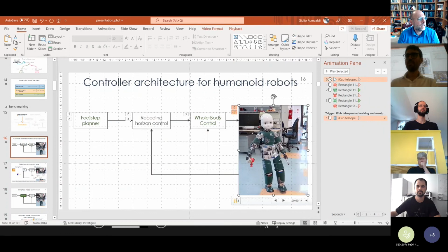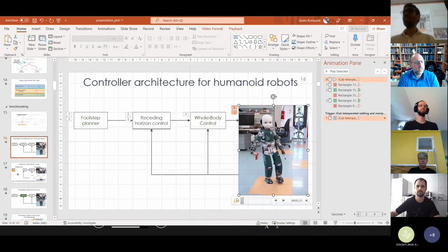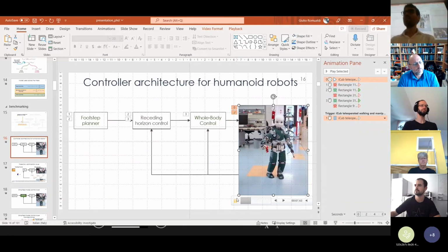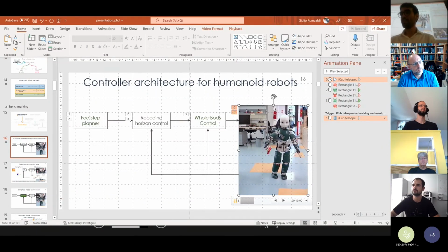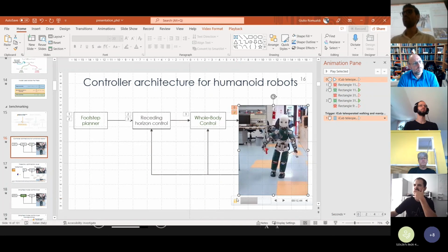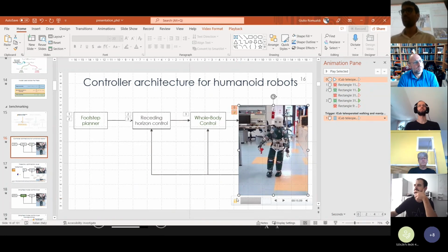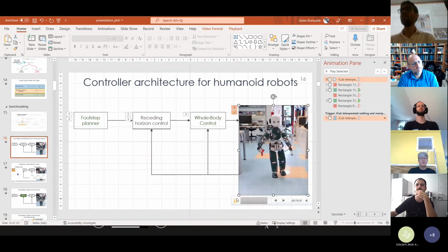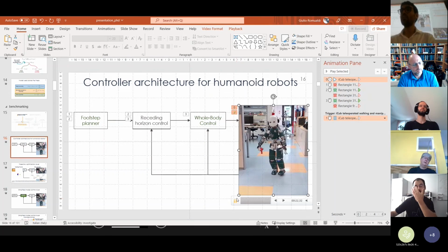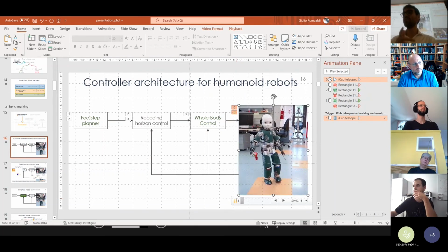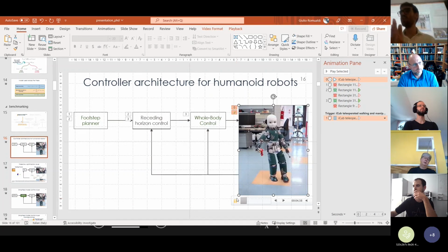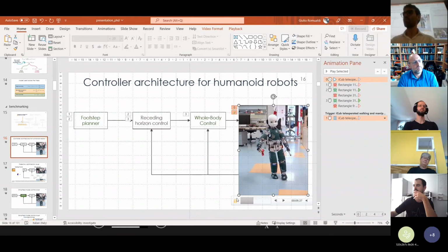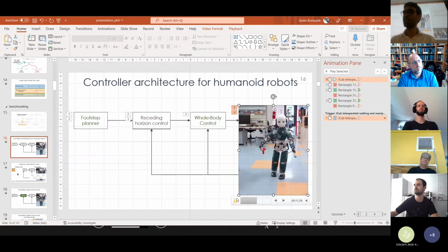Okay. So first of all, when the robot is controlling position, we don't try to regularize the angular momentum. So this could be one of the reasons why we don't have this swing motion of the robot arms. In the controller, we just regularize the joint position, and we have a task for the torso orientation. So the torso is kept parallel to the walking direction, and so that's probably the reason why we don't have this kind of motion that you are referring to.